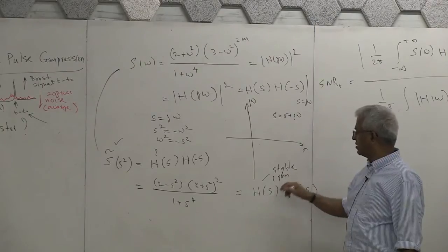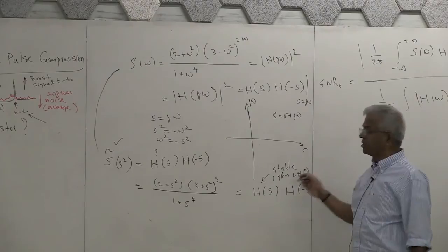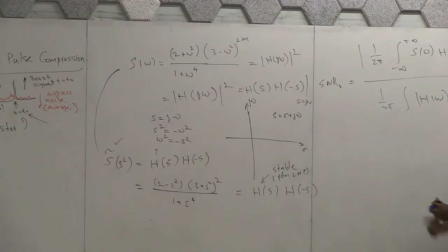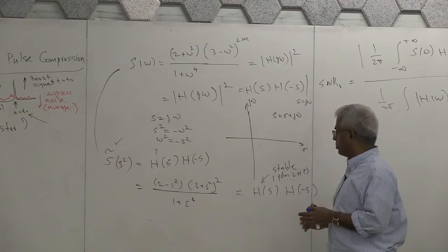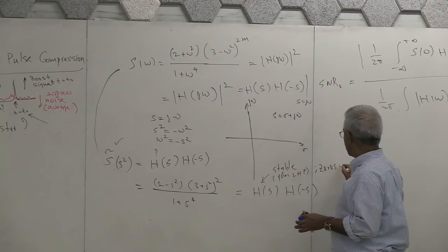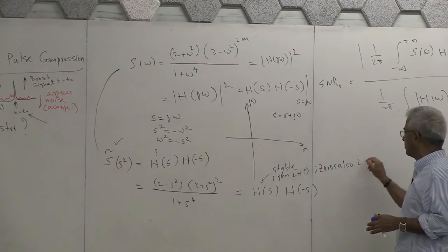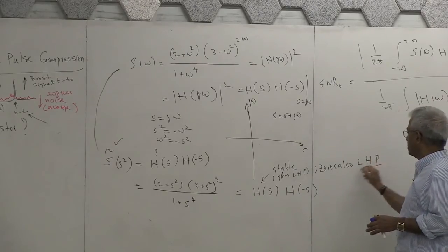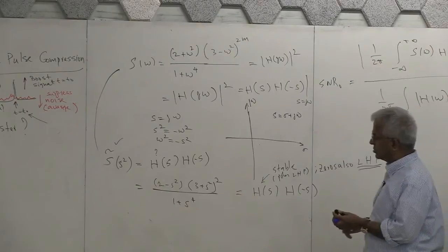Poles: if it is the discrete domain, they should all be inside the unit circle. And the zeros, there are no restrictions generally, right? But let's say, you'll see the reason soon, suppose we make the restriction that we also want the zeros to be in the left half plane. You can put them anywhere, but for the time being, poles in the left half plane, zeros in the left half plane. So let's plot the poles and zeros.